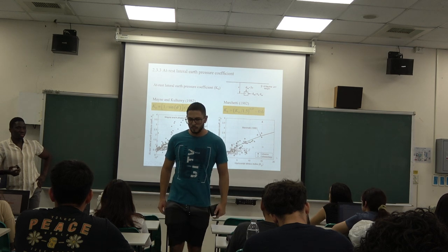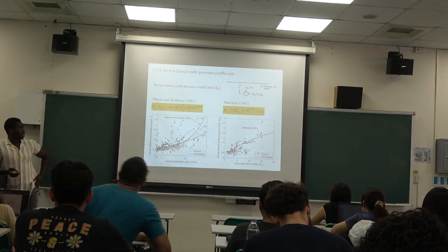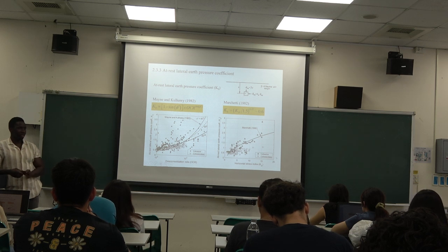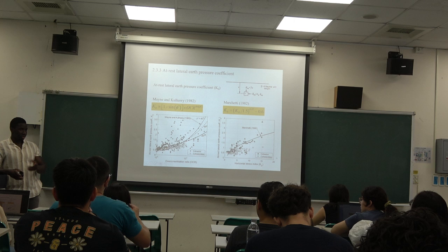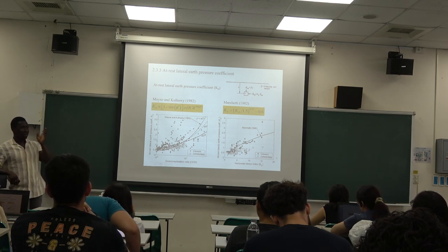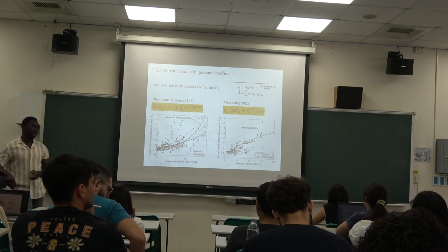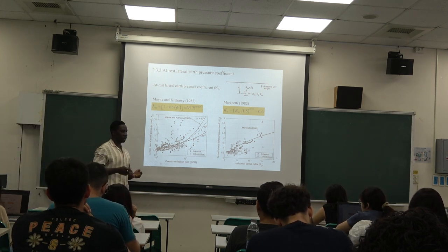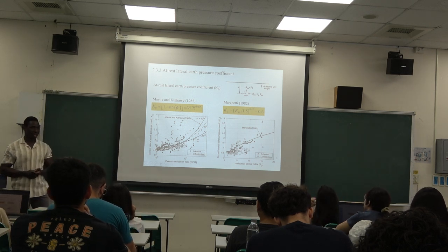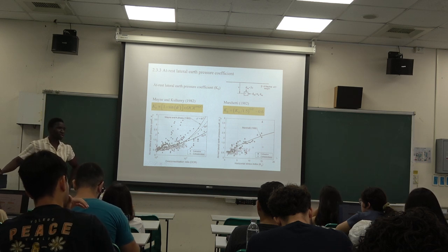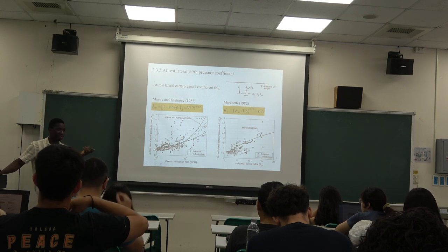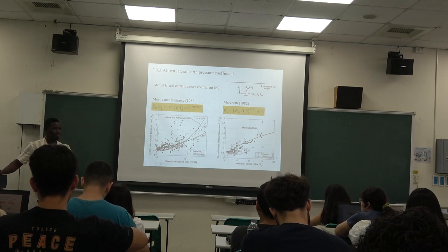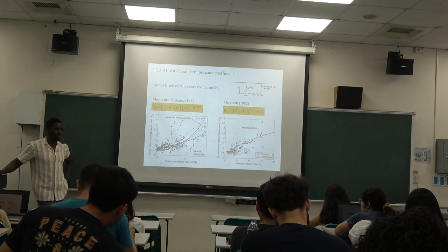So we will just quickly review what we did yesterday, and we will continue on from there. If along the way there is anything you don't understand, you can just ask. We are not in a hurry. I'll also show you some videos, because yesterday we were talking about the soil strength parameters. How do we determine the strength parameter, that is the friction angle or the undrained shear strength? We talked about using the SPT N, that is the standard penetration test, and also the cone penetration test. It's kind of difficult to visualize how the experiment is actually done if you don't really see it. So I'll show you some videos later that will explain in detail how they perform the experimentation, okay?